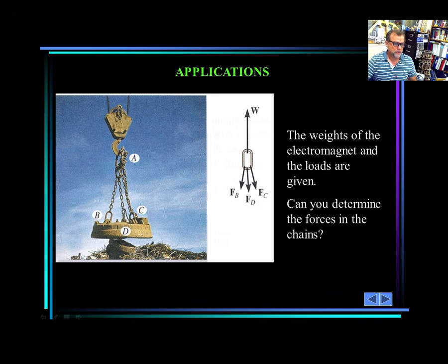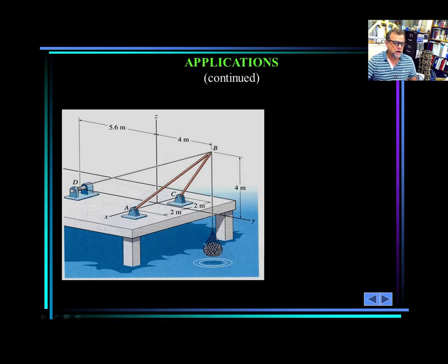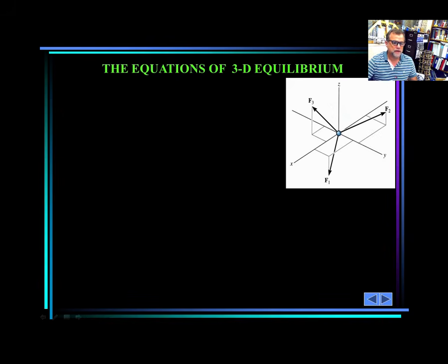For example, if you know the total weight here and you want to calculate the weight in each one of the cables, simple. Do particle equilibrium, establish a system of 3 equations with 3 unknowns, and solve the problem. How do I calculate the distance here? Well, 3D equilibrium once again at that point. And we're going to be doing that.